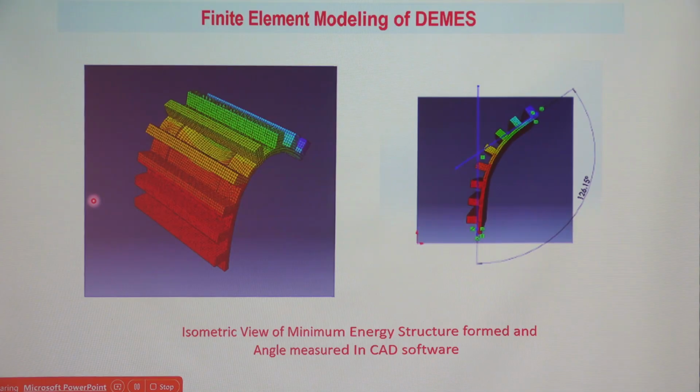Experimentally it's difficult to measure by using an online protractor. The reason is that the gripper is also there, and the actuator is also moving from the bottom side. So we developed an image processing technique to find theta 1 and theta 2 to get the accurate answer. But here in finite element, you can take an image and use an online protractor to find the angle. You're getting my point? So you see, we step by step keep on evolving. We provide pre-stretch separately, then we keep it as an initial condition in the second simulation and obtain the initial equilibrium configuration where no voltage is applied. Now the third part is very, very important.